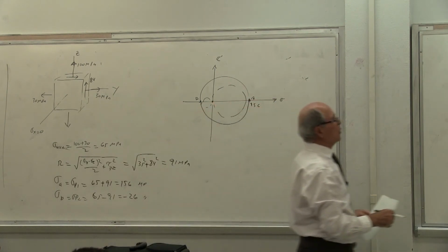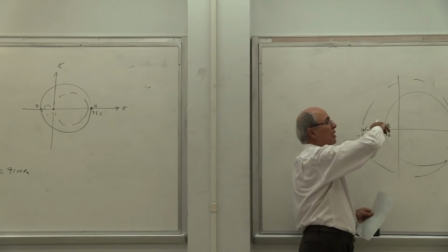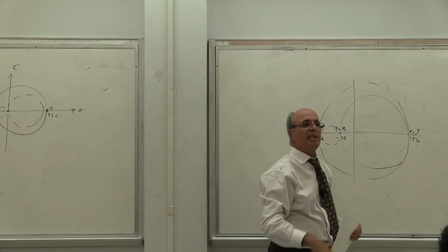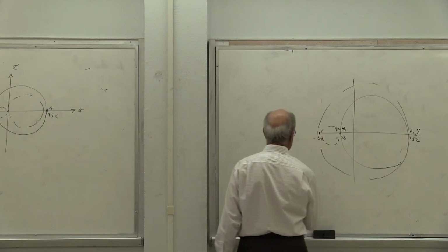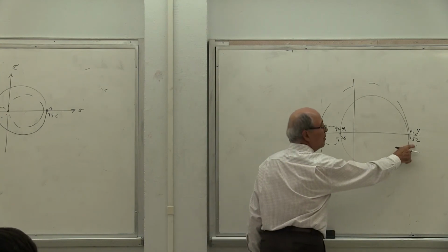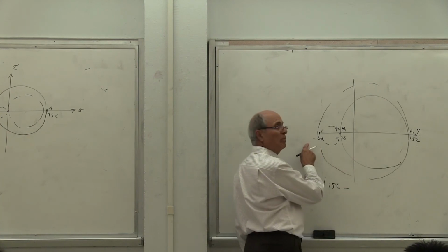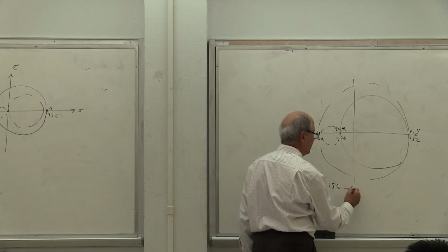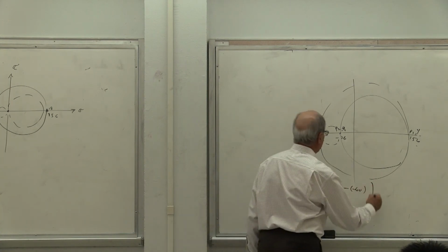However, here you are saying this is between y and x, so the rotation is about the z-axis. Is that correct or not? Therefore, what is the tau? That's what I want you to tell me. Tau max is equal to 1/2 of sigma max, which is 156, minus sigma minimum, which is minus 60, so automatically it becomes plus. That's why they add to each other.